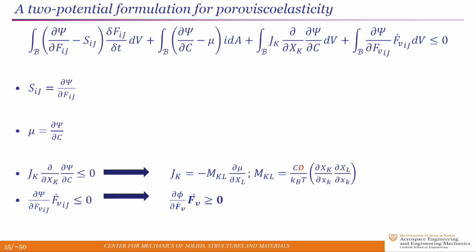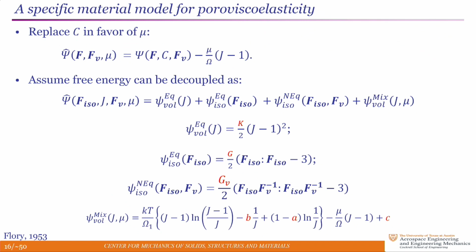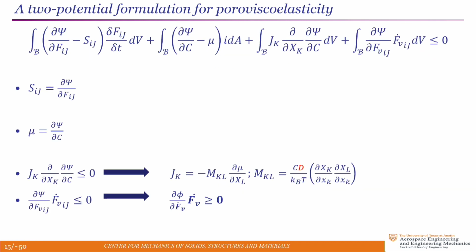At the deformed configuration, which is where the flow occurs, you use just a standard diffusion model based on the diffusion constant times the gradient of the chemical potential in the current configuration, deformed configuration. You map it back to the reference configuration, it becomes anisotropic, that the diffusion in the direction of tension is larger than the diffusion in the transverse direction, and so on. But those are things that can be managed in the framework of finite elasticity. So that's the general framework for forming the boundary value problem, closing the system with constitutive equations.